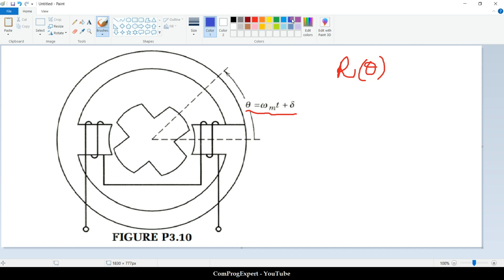So what is the magnetic equivalent circuit for this problem? When we excite this coil, for example, connect this terminal to the positive DC link and this to the negative one, we will have a field in this direction. Similar to the problems of chapter 1, you can consider one reluctance for the back iron, one reluctance for the pole, reluctances for the air gap, reluctance for the rotor core, and so on.